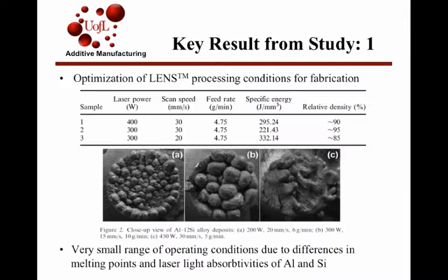And actually, they didn't show the optimized laser power. These are kind of the three different types of errors that they could produce. A is the low power, and they called it almost like a bubbling effect, where the surface tension of the gas is higher than the surface tension of the solid when it's interacting with the liquid metal. So, like water droplets, it forms little spherical bubbles, and as you can see, it gets even bigger when they increase the laser power a little bit. So it gets more power at the center and less power as it expands out, so it has more opportunity to form the droplets and doesn't solidify very well.